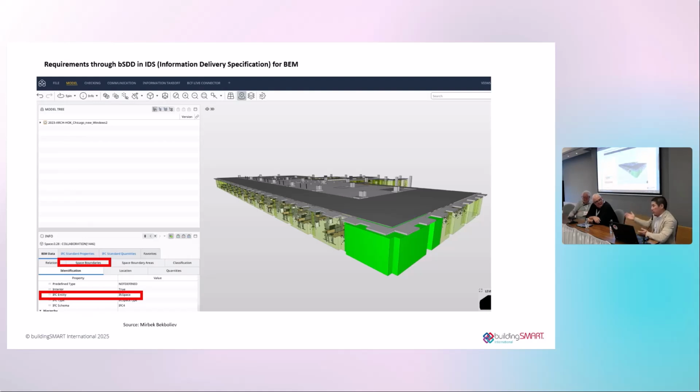And our architect wanted to have not only triple glazed insulated frame windows, but we of course suggested, in that climate, with a house facade of windows, in winter with a low altitude of sun, it will be overheating. So you will be freezing in summer in that case. It will be cool, it will be nice, but in winter you will be running there in t-shirts, so you have to think about overheating, and that's what we thought about in that case as well.